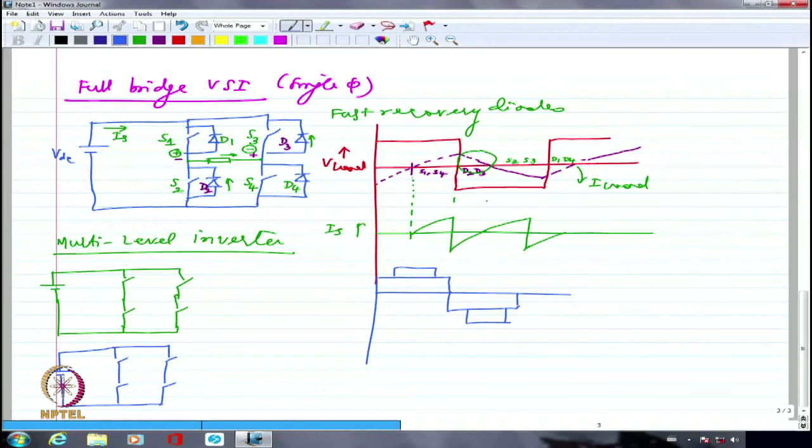So now what I can do is, this is one end of the load terminal, so let me take that out, and from here I can connect it to this, and from here I can connect to the load. So here I can connect my load. Right? I'm essentially connecting the two outputs in series. You imagine whatever we did in auto transformer, something similar. What we are doing is essentially connecting one end of the load here, the other end of the load here, and in between we are connecting them in series. That's it.